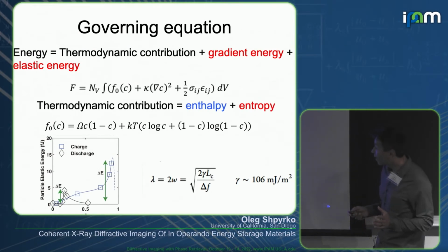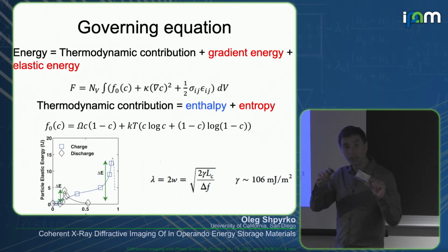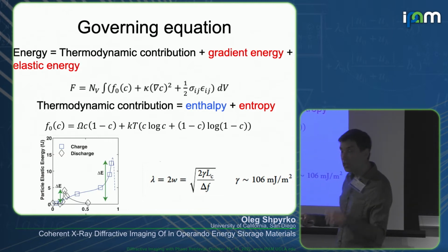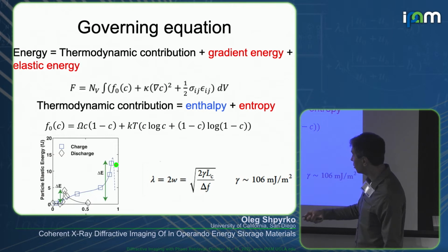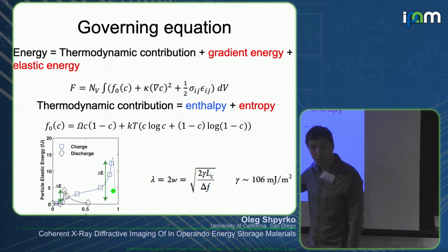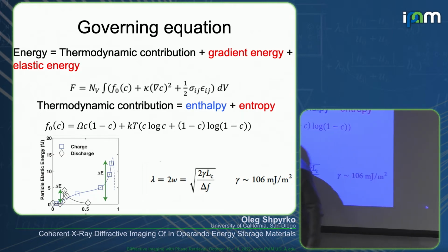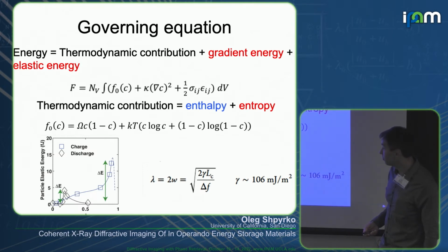think about it. The other thing that is really cool is that because we measured the elastic property of the entire particle, we know what the distortion of the particle is in 3D for every point of charge and discharge. We effectively have a total elastic energy of the particle as it goes through this charge-discharge process. And by integrating over the full 3 dimensions, we can get the elastic energy shown here as we're charging and discharging. You can see that there is a barrier that it tries to overcome, right? And that's the origin of the hysteresis that we still don't fully understand, which we measured with femtojoule resolution, if I may say, because we measured the elastic fields with such high precision for a very small particle.